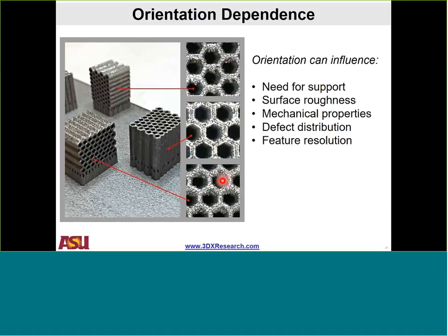But in a cellular structure, this could change your thickness by 10% or 5%, and most of our stiffness properties go by the cube or the square of thickness. So a small change in thickness can have a large change in measured properties, especially since this geometry is repeated 200 times or more, thousands of times throughout your cellular structure.